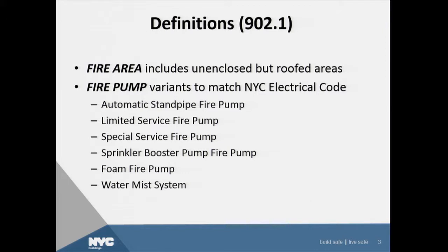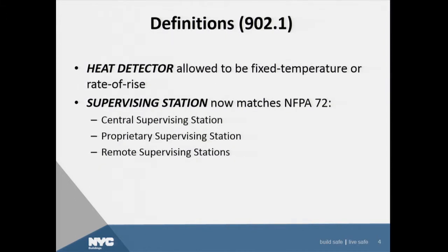The term fire pump now matches the electrical code and with respect to an automatic standpipe fire pump, a limited service fire pump, et cetera, et cetera, et cetera. For those of you who are fire protection engineers, that may be more important than others. Okay, so the heat detector now makes it clear that the activation can be a fixed temperature or a rate of rise. And that's important when you're talking about different types of environments where you need to select the right kind of detector so you avoid those false alarms.